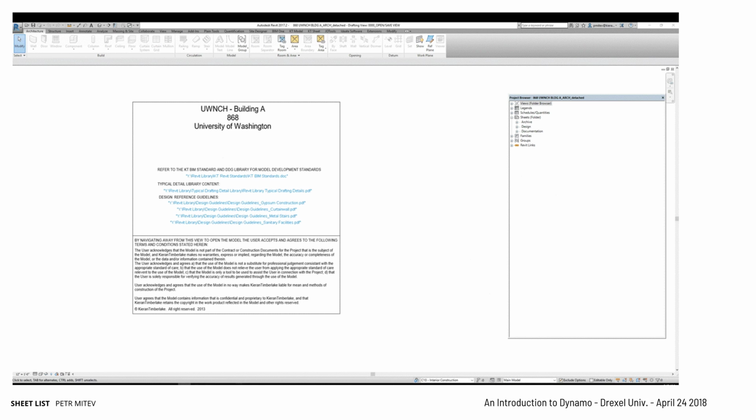And the unfortunate animation that won't show right now is a Dynamo graph that lets you select a folder or a bunch of folders. It will loop through the drawings, and based on typical architectural convention, it will create an Excel of numbers and names. It will also generate those lists for you directly in Revit if you want to schedule them as dummy sheets or something like that.